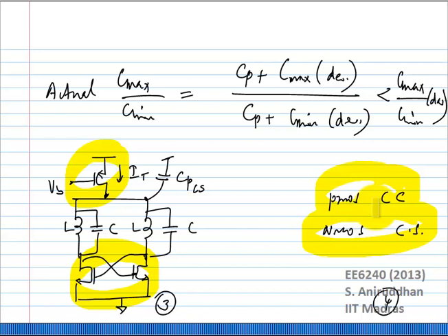As it so happens, so far we haven't seen much to choose between the two, except for the fact that the PMOS will be 3 times larger than the NMOS for the same negative resistance, and therefore it will have larger parasitic capacitance and smaller tuning range. That is the number one difference we have seen in the cross-coupled pair.